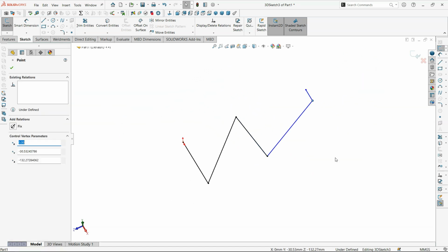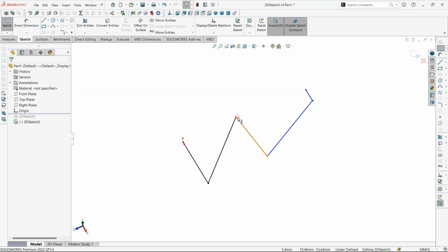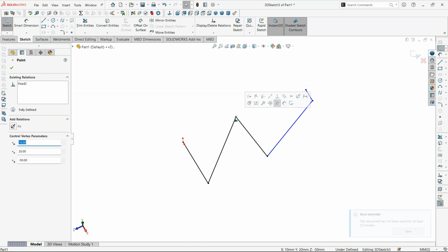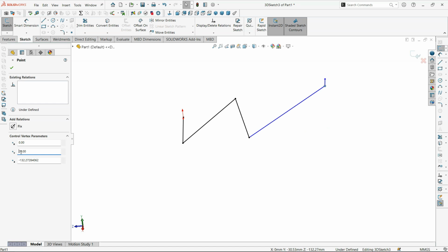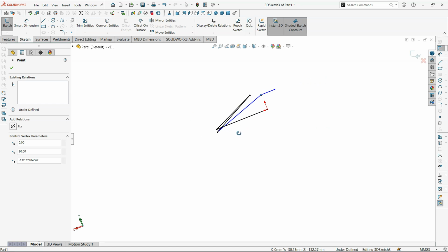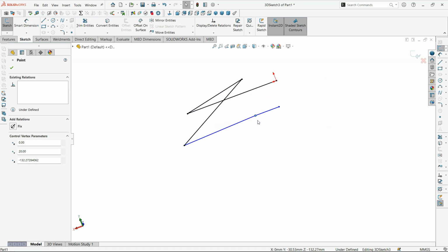By clicking on fix, you see we have generated it, and we again want y to be equal to this point. So y over here was 20, so I will again select y 20, but not negative, positive y, so I will just remove the negative sign,